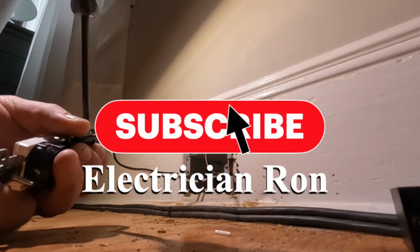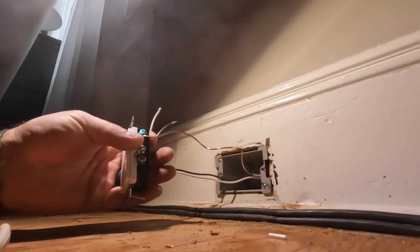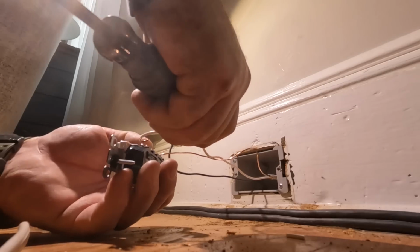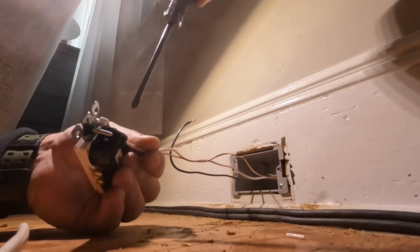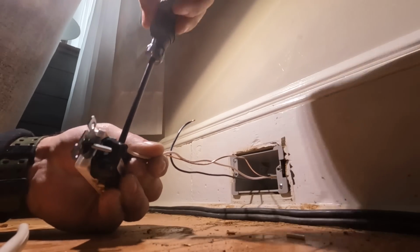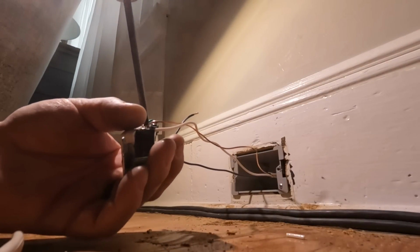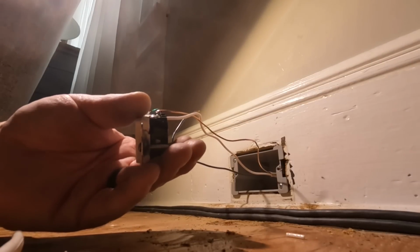So anytime I replace a receptacle like this, I'm supposed to bring it up to code, so that's exactly what I'm doing. Obviously the bare conductor you see that I'm tightening up, that's the equipment grounding conductor. That's going directly to the receptacle. Because the box is plastic, it's not conductive. We do not need to bond or ground the box because it's plastic and it won't conduct electricity. The other two conductors is the neutral, which is actually a grounded conductor, different than the equipment grounding conductor. And then of course finally the hot conductor, electricians will call this the ungrounded conductor.